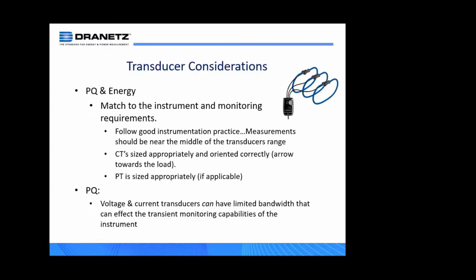So it takes a current primary and puts out a current secondary. But we use the term CT all the time. I'll probably use it until the day I'm no longer working here. I'll call a current probe a CT. But the important thing here is to make sure that your CT is appropriately sized for the load. So in other words, if I have a current probe or a CT that might be rated, let's say, 1 to 3,000 amps, the thinking is that, hey, I can use this CT to monitor 1 ampere of current.